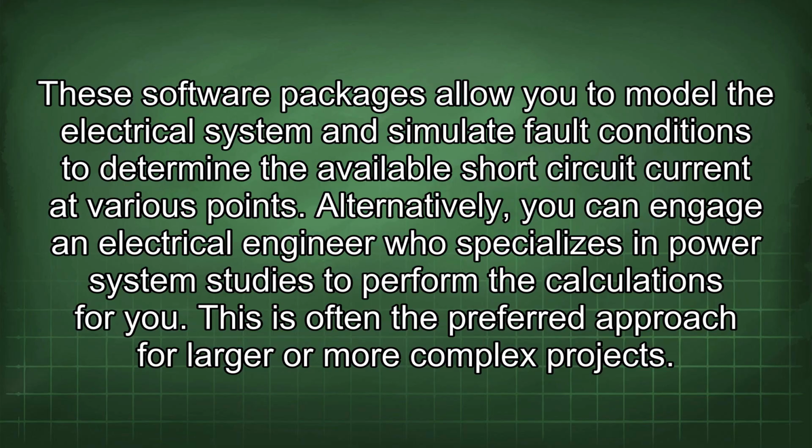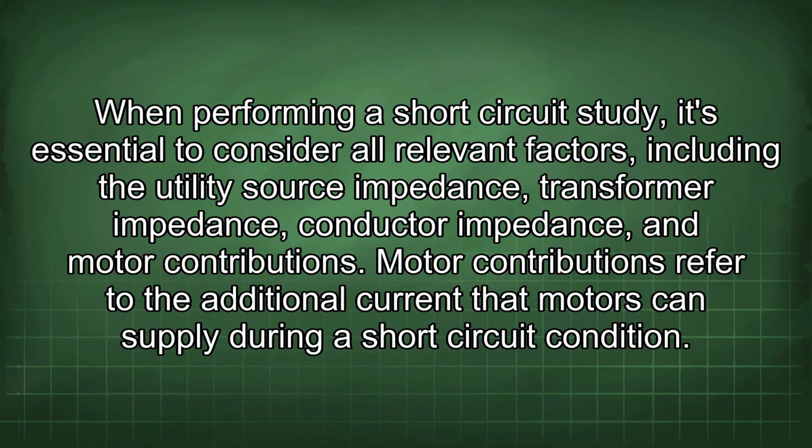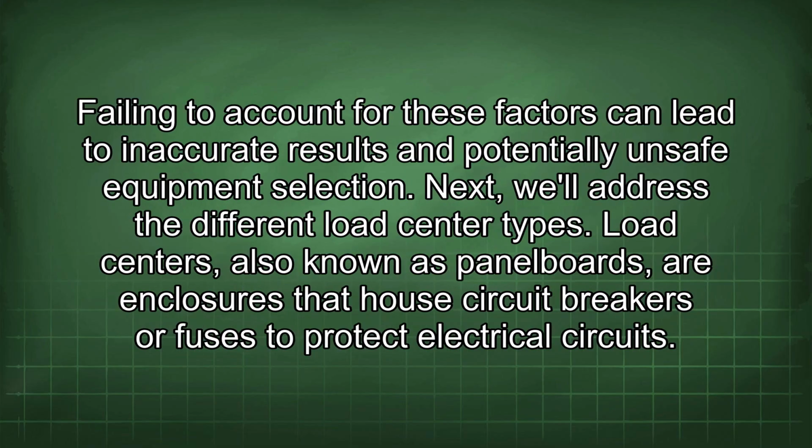Alternatively, you can engage an electrical engineer who specializes in power system studies to perform the calculations for you. This is often the preferred approach for larger or more complex projects. When performing a short circuit study, it's essential to consider all relevant factors, including the utility source impedance, transformer impedance, conductor impedance, and motor contributions. Motor contributions refer to the additional current that motors can supply during a short circuit condition. Failing to account for these factors can lead to inaccurate results and potentially unsafe equipment selection.